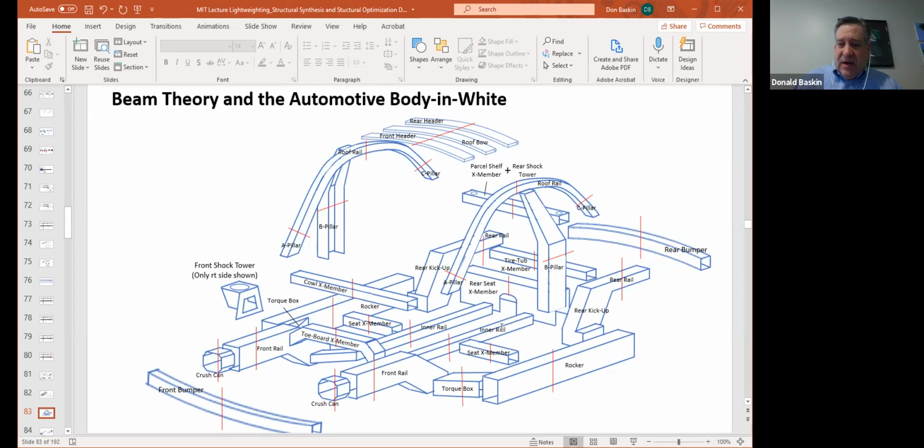Typically, it's easier to make a car meet rear impact than front impact. For most cars, obviously this isn't the case with a rear engine car like a Porsche 911, but there's much more metal to crush in the back of the car than in the front, because there's no engine in the back most of the time. Most gasoline powered cars take up that load very easily in the rear because they can crush and dissipate lots of energy.